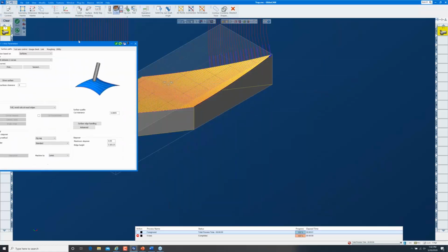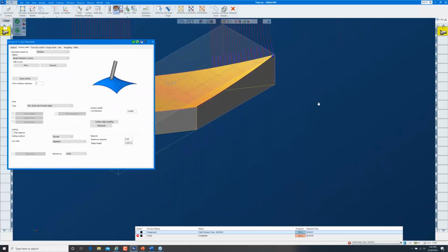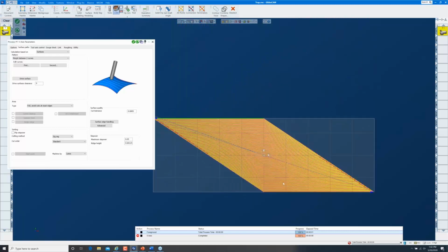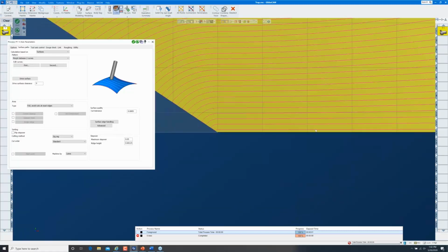All right, so a couple of things that I want to show you here. First off, we have a lot of retracts. The second thing is that this line, this edge is straight, but these strokes are curving around that. As they exceed it, as they go past it, they start wrapping around it because of the way offset toolpath is handled.